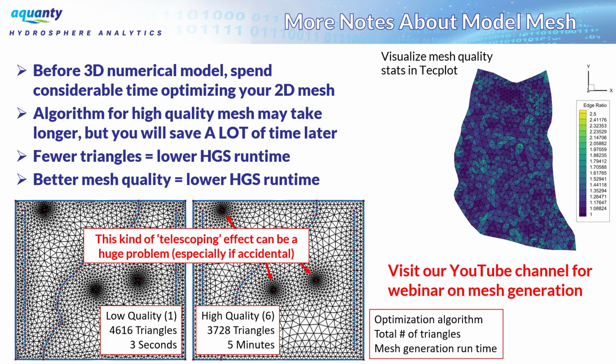So there's two aspects that you really need to consider whenever you're building your mesh. First of all, you want to have fewer triangles and fewer nodes in the mesh. Of course, you always want to refine around areas of interest, but if you can cut out nodes in other areas of your model as much as possible, that's going to lead to lower HydroGeoSphere runtimes. The second thing to consider is the mesh quality.